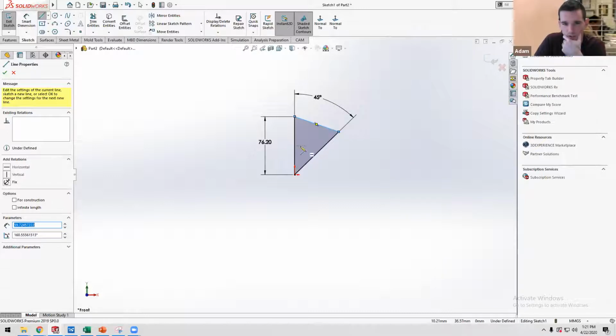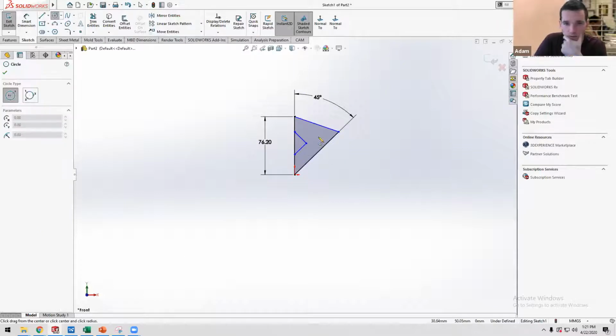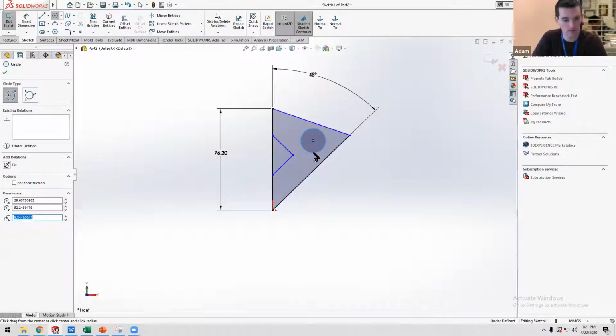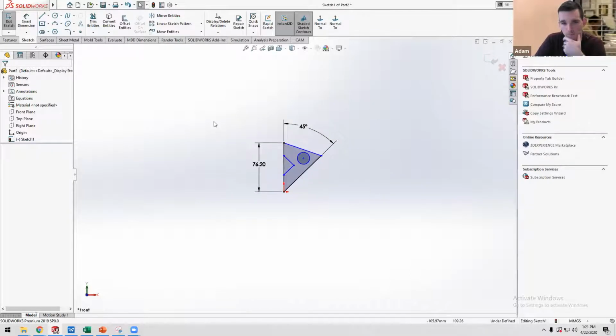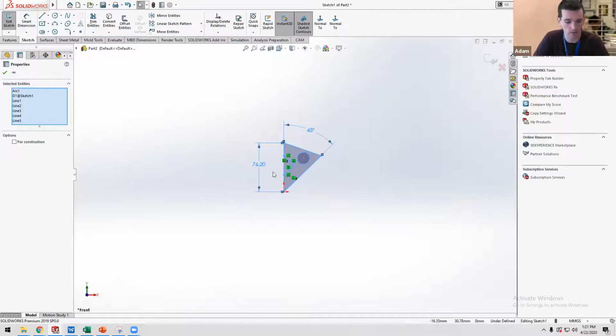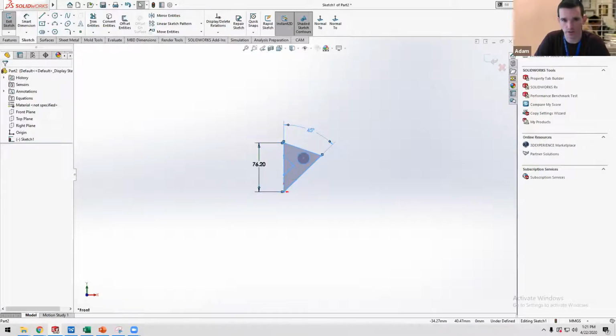And now we're going to imagine these are scissors, and we're going to cut out little shapes. Okay, something very basic. What I'm going to do is use the mirror function. I'm going to highlight this geometry, hold Control, click these 2 dimension tools. I don't care about those.